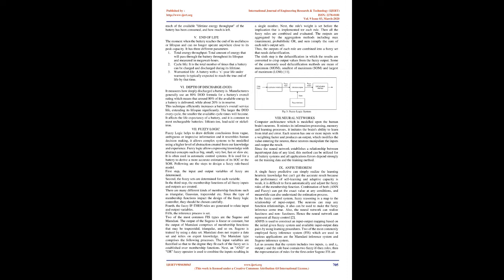Linear model. Lead PV. Online, cheap. Needs reference data for fitting parameters. Artificial neural network. All battery systems. Online. Needs training data for a similar battery. Impedance spectroscopy. All systems. Gives information about SOH and quality. Possibility of online measurement. Easy. Temperature sensitive, cost intensive.